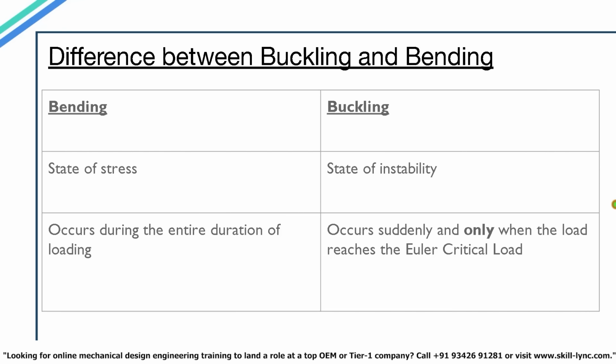Now let's do buckling. Let's position our scale in a vertical position like this and provide support to it so that it doesn't fall. Now let's start adding more and more load to it from the top. You can notice that initially the scale does not deflect, but after a certain load, it suddenly bends to the side. Why? Well, simple. It just reached the critical load of buckling.